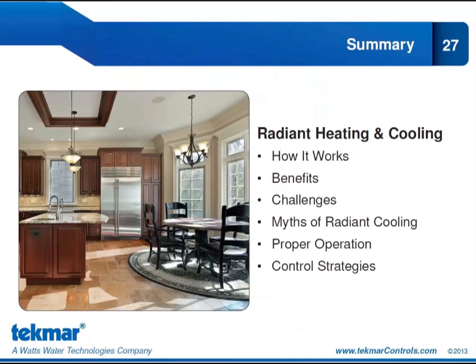We talked a little bit about the proper operation, and the big takeaway there is that a radiant system must be combined with a forced air system. So don't install a radiant heating or cooling system on its own. We need it typically for the heating side to satisfy the heating load. And we definitely need it when we talk about radiant cooling to address the latent cooling load, and potentially to provide part of the sensible cooling load as well.